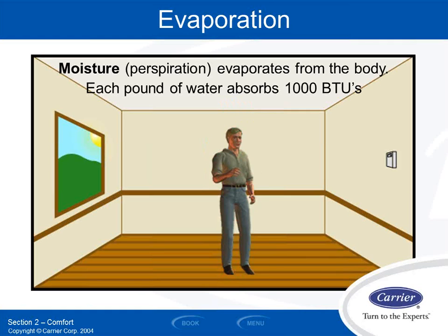We do use evaporation in HVAC processes. The biggest example of that is probably a cooling tower, where we have a chiller system and we send 95 degree water to the cooling tower, and we mist it out into the air and use fans to run the air across the mist and let it evaporate out the heat, and basically whatever condensate is left, we return as 85 degree water. We cool it down 10 degrees with just evaporation.